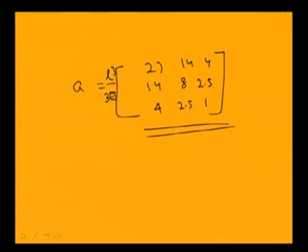Today in class we have studied the 3 degrees of freedom systems. We have found the eigenvalue and eigenvector. I told that this eigenvector can also be determined from the adjoint matrix. For a given system M K, you can find first the A matrix, which will be equal to M inverse K. After finding this A matrix you can find the eigenvalue and eigenvector.